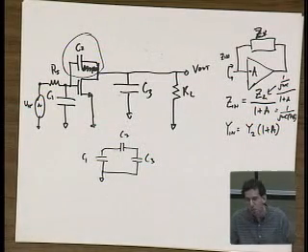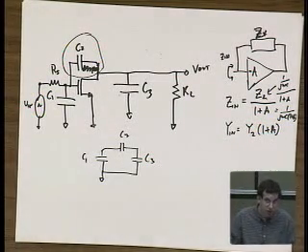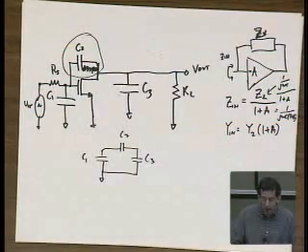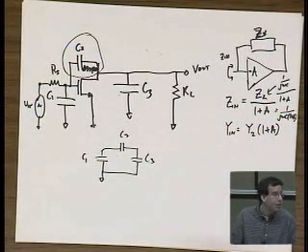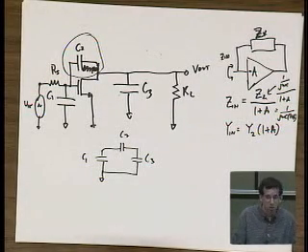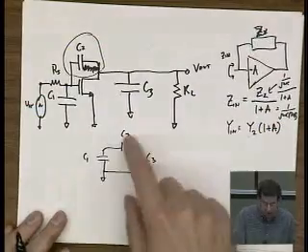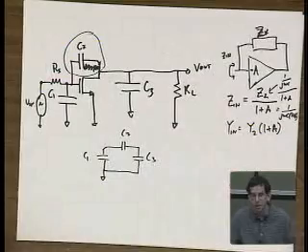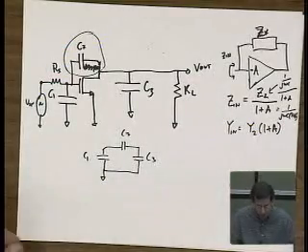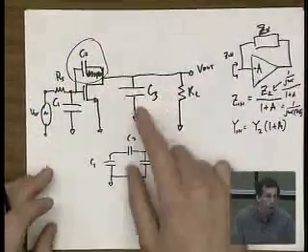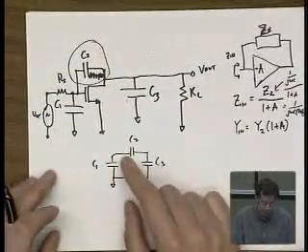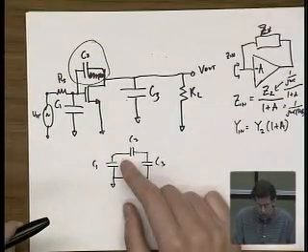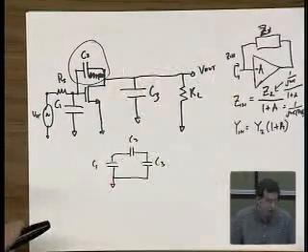Another way, more generally, is that how many capacitors there are will generally tell you, although in this case it'll mislead you. How many nodes there are is a general indication, because in this case it's only because there are two interesting nodes connected to capacitors that you're limited to two poles. Anyhow, a more rigorous method is to actually do this, and anyone who's interested as to why that's the case, I can talk to offline. So boom, we know we've got two poles.